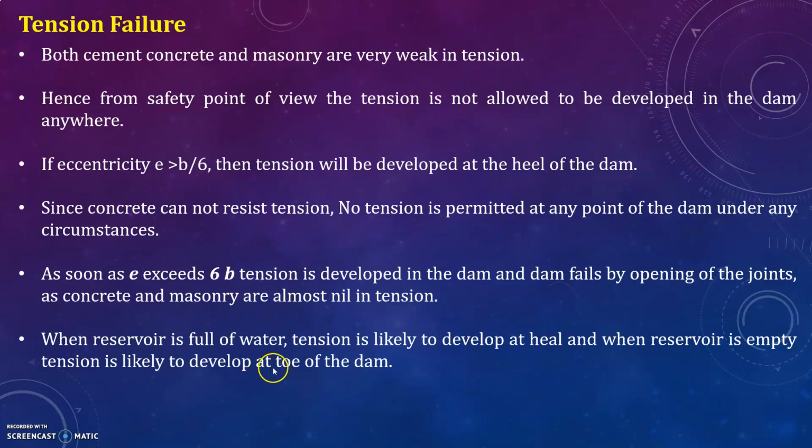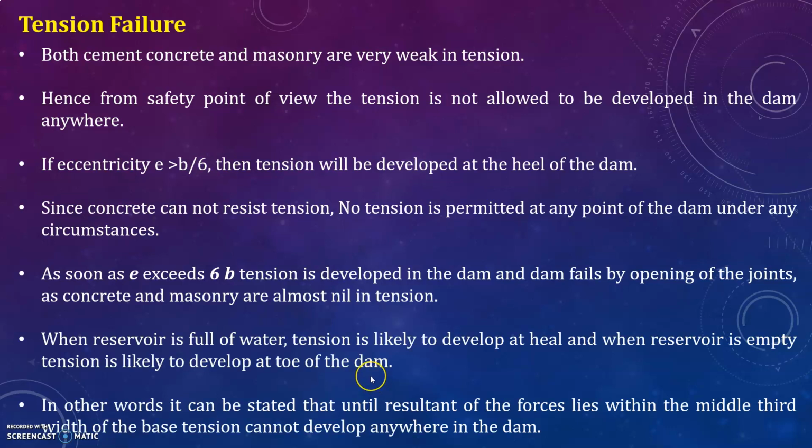When reservoir is full of water, tension is likely to develop at heel, and when reservoir is empty, tension is likely to develop at toe of the dam. In other words, until the resultant of the forces lies within the middle third width of the base, tension cannot develop anywhere in the dam.